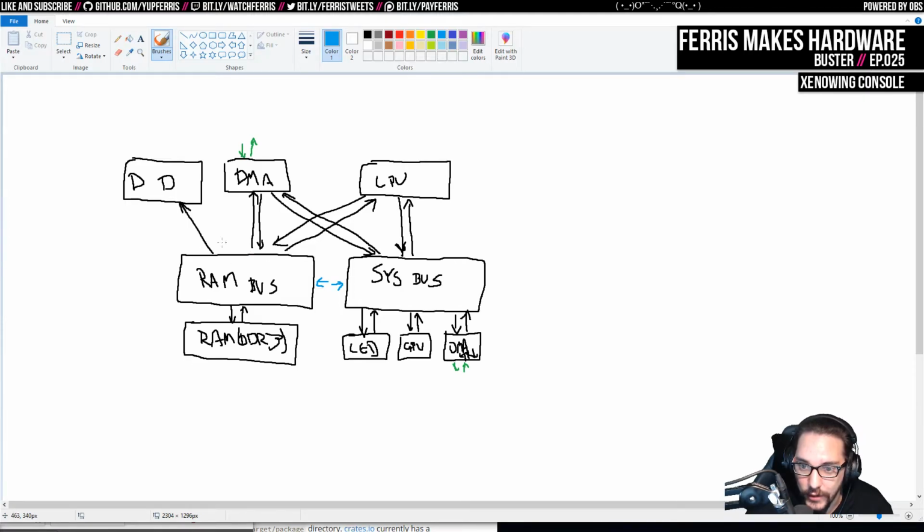And there's also some priority here. So for example, the display DMA is going to be really timing critical. That's basically every scan line that we're going to output pixel data that needs to go and read the RAM and get that pixel data as soon as possible. So it's going to load that into some buffer that's also being read from for the actual display hardware.